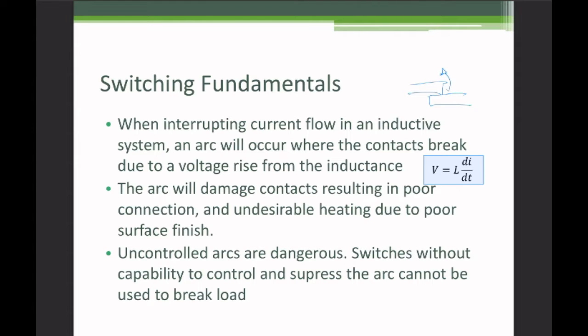Now, when electrical contacts are closed, they need to have a really good contact right in here. This needs to be very smooth and very clean so that the electricity can flow through without any resistance. If you end up with resistance, you end up with localized heating right at your interface. If things get hot, a couple things can happen.